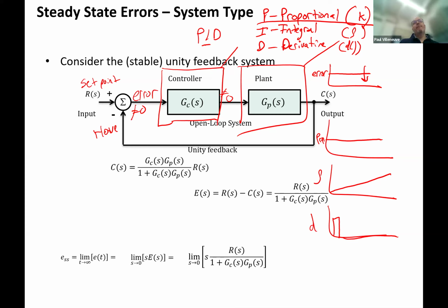Well, I can do that with proportional and integral, and I can see with proportional and integral control, I can force the error to 0. When do I add a derivative control part of it? This is a tough one. Well, you don't know if the error is going to change, right? That's the thing with a controller. It has to be able to go for all cases and conditions.